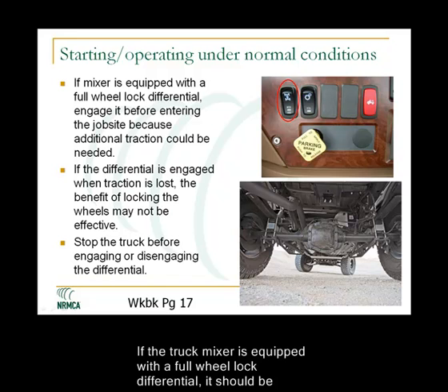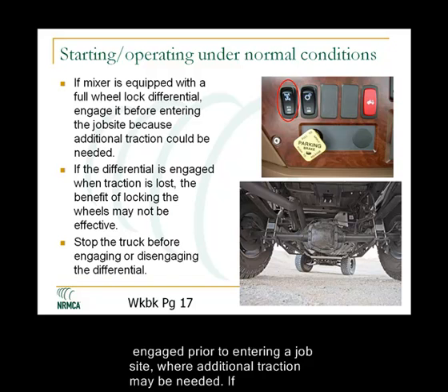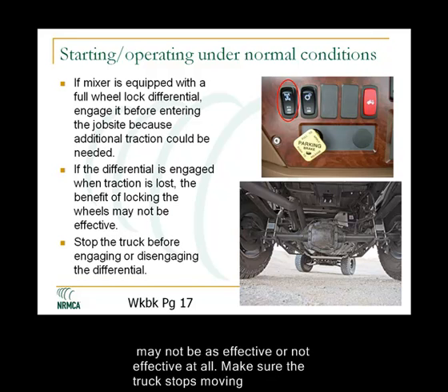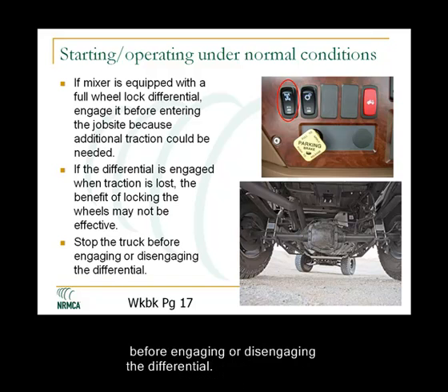If the truck mixer is equipped with a full wheel lock differential, it should be engaged prior to entering a job site, where additional traction may be needed. If the differential is engaged when traction is lost, the benefit of locking the wheels may not be as effective or not effective at all. Make sure the truck stops moving before engaging or disengaging the differential.